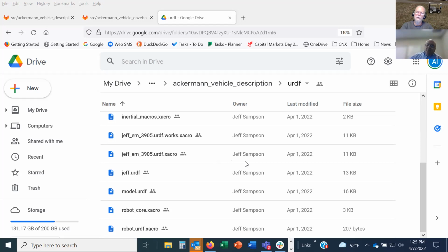I always put it in my bashrc, so as soon as I open a terminal window, it knows to go to the correct workspace. So I just go into the bashrc, go down to the bottom and change it from catkin_ws to catkin_ws_sim, and then it'll use the new workspace. And anytime you can switch back to your other one.